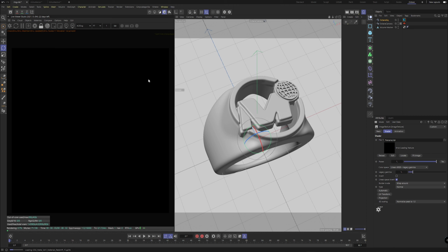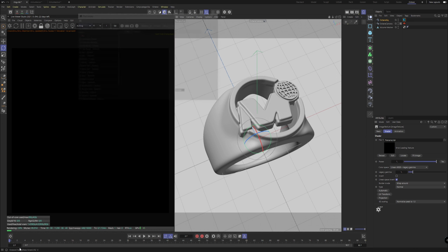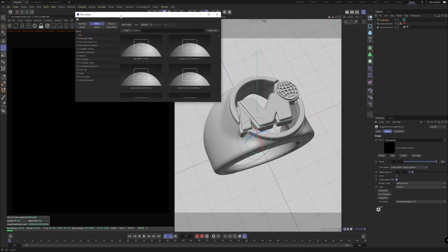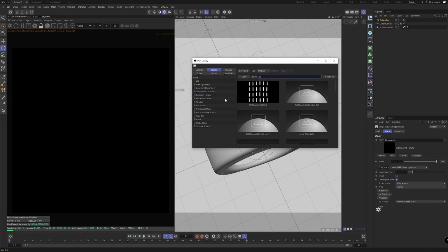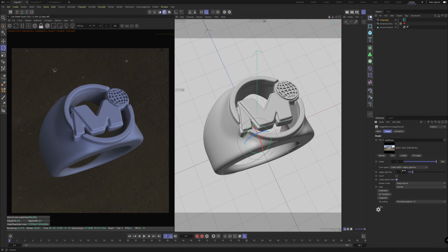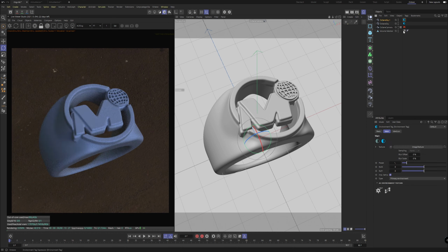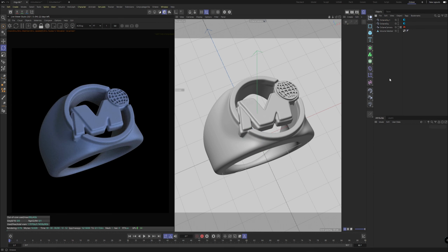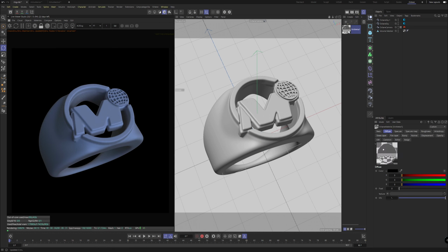And once this loads down here, it always takes a minute to load for the first time, we can start picking through what we have. So super useful if we head to HDRI and literally search graffiti. We have a graffiti one, so we can drag that into our file name here. It's a daytime one too, so that should work quite well. We can set this to ACES. Doesn't matter about the rotation as such for now. We can head to this, clear it, so we've got a black background that we like. It's invisible. And literally head to materials here, create a metallic material, see what this looks like.